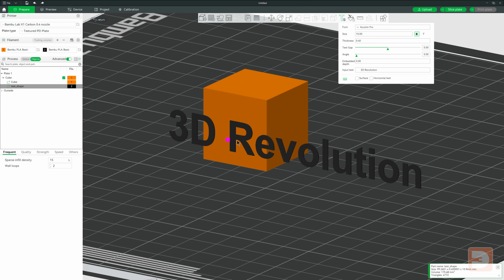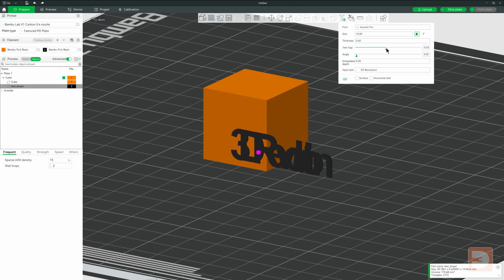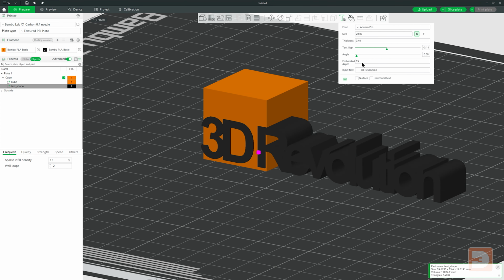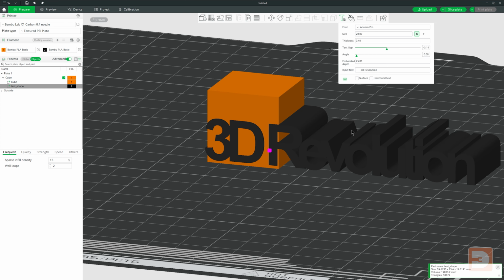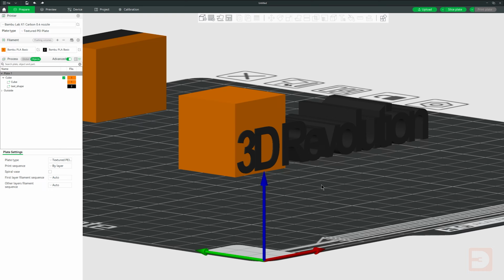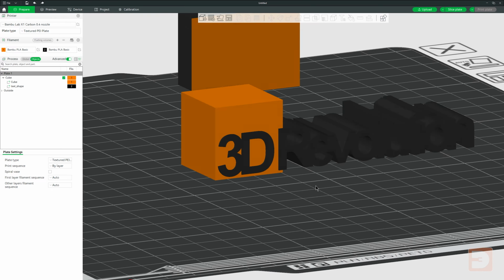You could then adjust the letter spacing so that the letters are physically touching, extend the embedded depth figure to be the same as the object depth, set the thickness to 0.01mm, and then you can have the text start as a flat coloration on the side of your object and continue out the side in 3D.